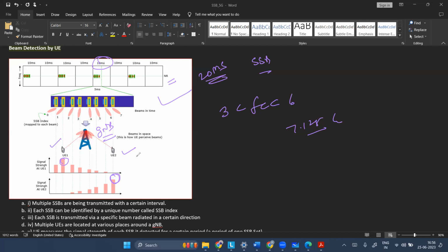This could be pretty beneficial compared to 4G, specifically for scenarios where you would have very low RSRP or RSRQ. But in this case, you can confine your beam toward the particular location where your user is situated. This specifically comes in handy when the throughput requirement is high.